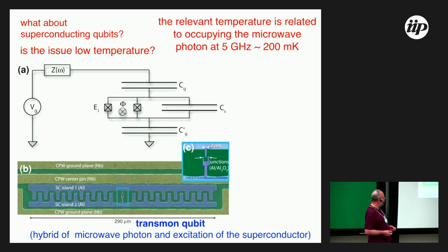and that's because you need that in order to get a good coherent microwave photon. As is often observed, this already looks huge, but in fact this is one of the smaller early transmon qubits. Now they are often 10 times bigger, because the bigger you make it, the longer the coherence time is going to be. It just makes everything really slow, though, because the nonlinearities also get smaller, which means the detuning that you can work with is smaller, which means that everything takes a long amount of time. So the superconducting technology is in a really tight box. And the basic problem is that these things are all big.